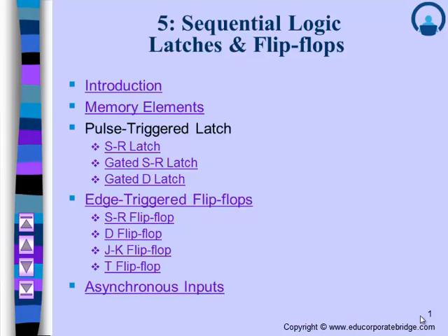First of all, sequential logic circuits are those circuits which have memory elements. That is, they store memory, or they store values from the past. So the outputs of sequential circuits depend on the current values as well as on some past values. That is the reason they are called memory elements. Most of the circuits, like flip-flops, are used to store bits, therefore they are called memory elements.